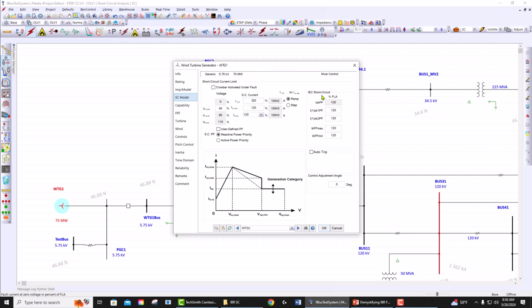When it comes to the IEC standard, we also have different scaling factors for different fault types. So we have a scaling factor for line to ground, for line to line, our double phase faults and double phase to ground, and three phase fault max and min. The way that this works is that if the max current here on this I short circuit max is equal to any of these currents, it means that the scaling is 1. There won't be any difference in this curve.